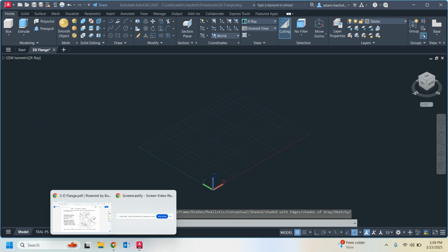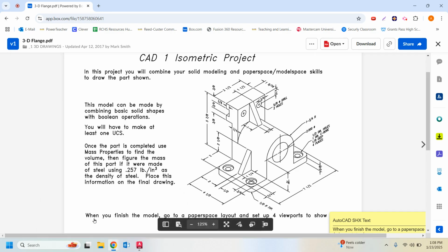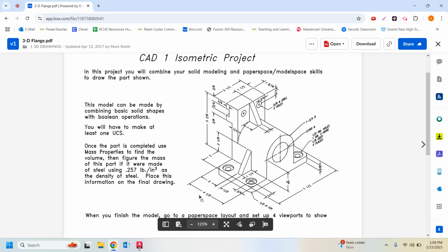Let's take a look at that first box and our dimensions. So we need to make a box. First of all, I want to point out we've got some fillets around these corners. We're going to do those toward the end. You usually want to take care of fillets last if you can help it. And the same for chamfers. You want to go over stuff last. If you do it too early, then you can have trouble if you need to do some work from that corner.